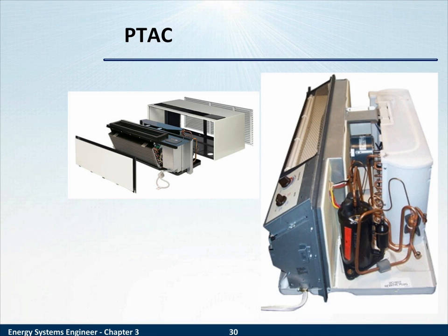Some of the components of a PTAC include, of course, a compressor. You still have to have a refrigeration cycle in this little component. There's a fan, a heat sink. It's like an outdoor unit except the compressor sits next to the coil instead of inside of it. And they often include as well an electric heat for reheating in the case that the air outside is too cool.